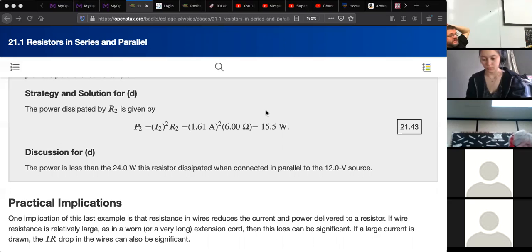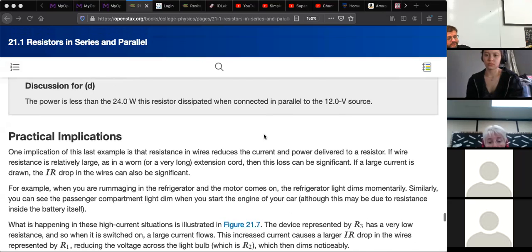Because if a resistor is in your circuit and it is designed to dissipate 1/2 watt, and it's actually supposed to dissipate 15.5 watts, that 1/2 watt resistor will burn in a real quick hurry. You'll get smoke coming out of it. And if there's one thing I've learned about electronics in the years I've done electronics, it's you don't ever let the smoke out of the electronics, because the magic smoke's what makes them work right. Without that smoke, they don't work.